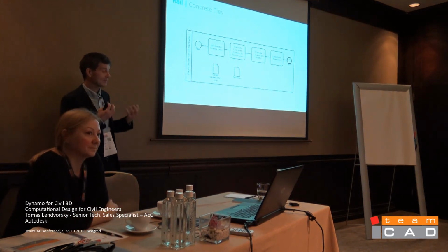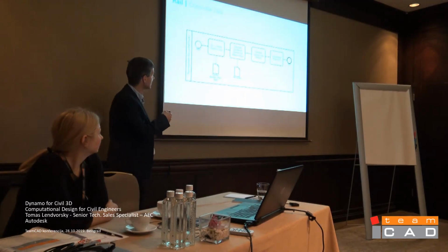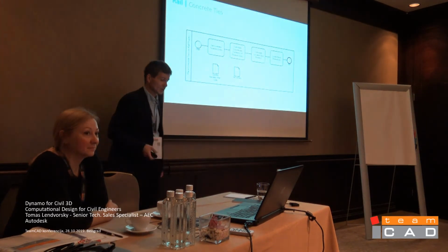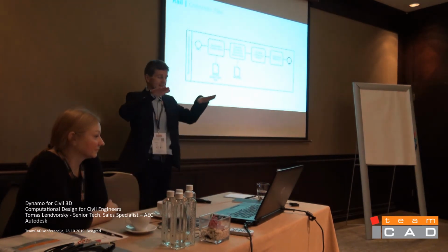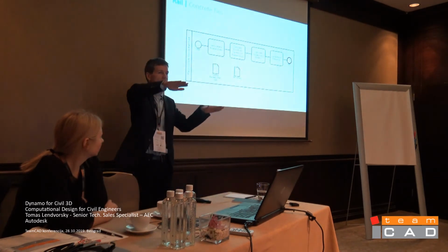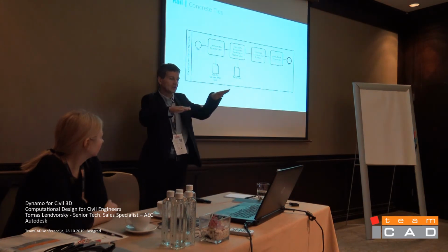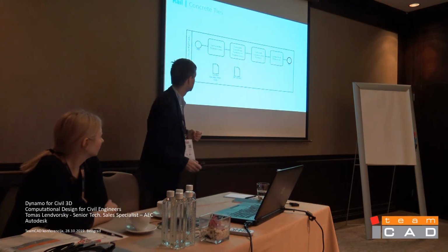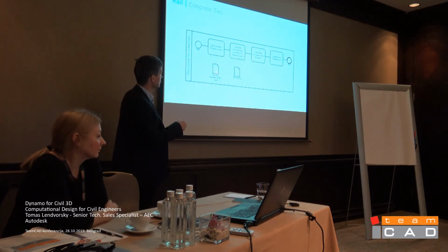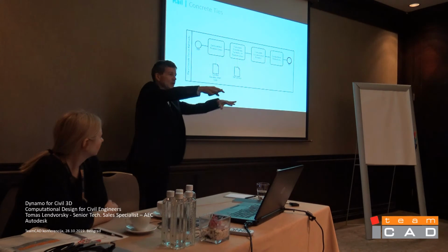If you think about it at the beginning, what you can do is get these input parameters. Basically, you can get corridor feature lines. Because if you want to make these ties, of course, you need to know where the rail track is going, but also what the cant is, or maybe say the super elevation, of the rail track. This is something which you need. And of course, for this you need the corridor baseline and point continuum. Basically, you have to know which feature line you are talking about.